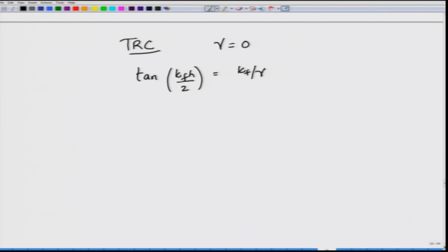A similar equation of course will have to be written for the transverse magnetic modes, or the TM modes as well. And what you see here is that the left hand side is a periodic function, and since gamma is equal to 0 in this particular right hand side, 1 by 0 will be quite a large quantity, in fact it would be infinity, and it does so when kappa f h by 2 goes through different values, right.